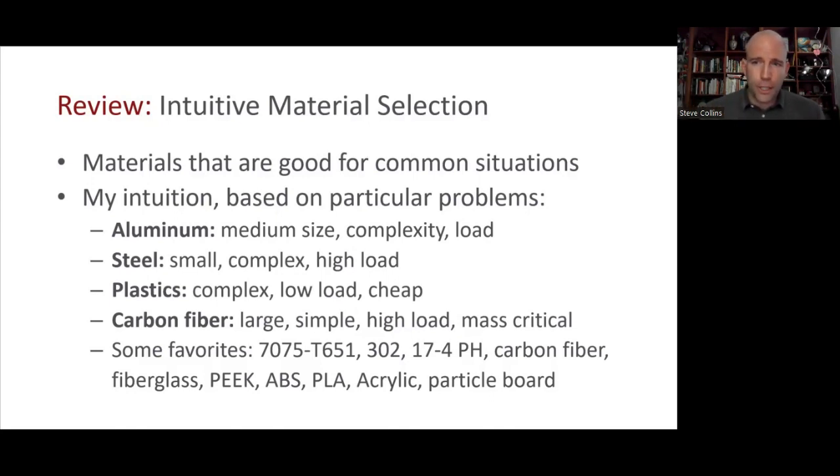Close to like heat treated 440C almost. Carbon fiber, good for high strength and stiffness applications. Fiberglass with an S class makes great leaf springs. So if you want it to be a little more compliant, fiberglass is a good choice.